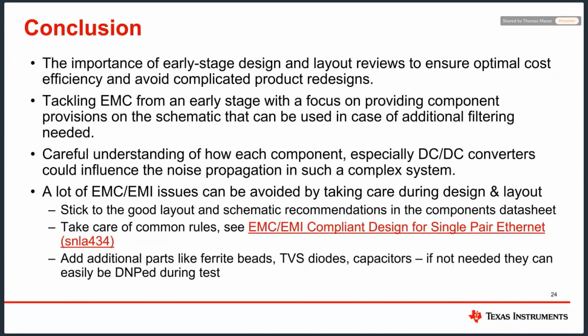And also, I would say it does not hurt to add provisions like ferrite beads, TVS diodes, and capacitors to your design as a safety measure. Later on, if you don't need them, you just unpopulate them. But it's always good to have a place to solder them on during the tests.